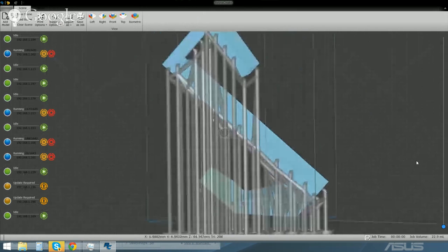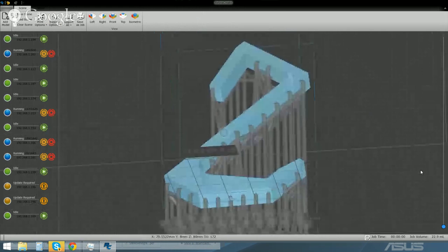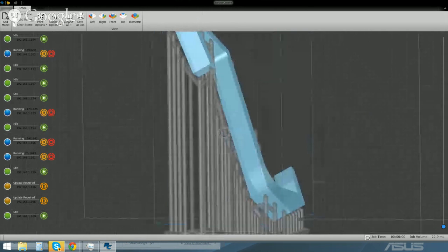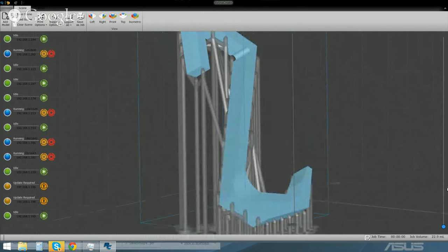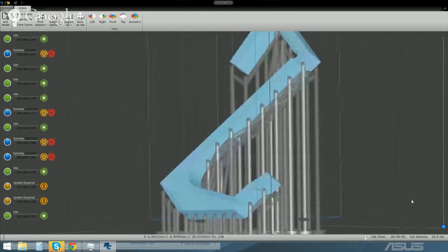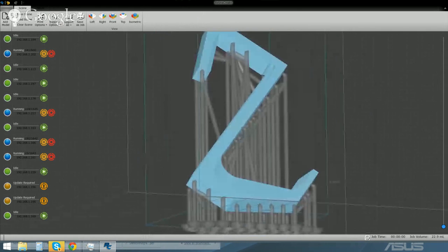And you can delete some of these columns and save yourself some resin that way as well, and use the automatic support less. But the best way to save supports, but maybe it's a little bit dangerous to do, it increases your risk of build failure for sure, is you can place your own and place them fairly sparsely. But if you get them too sparse, then there is some chance of a print failure. So that's why there's so many supports when you do automatic support placement.